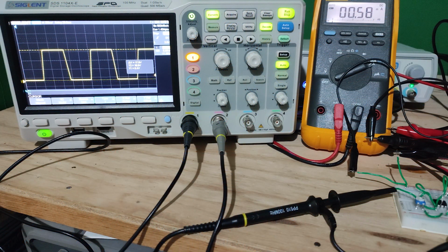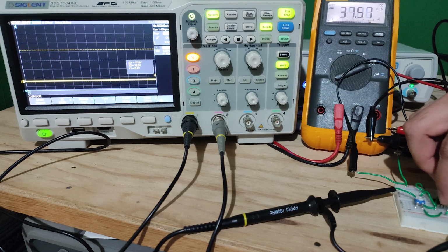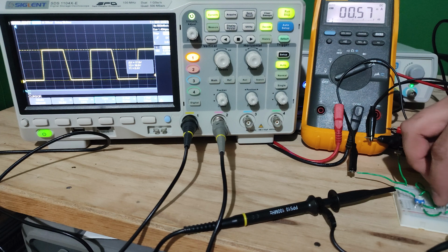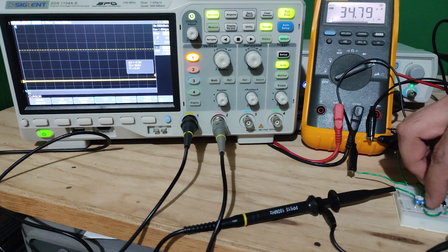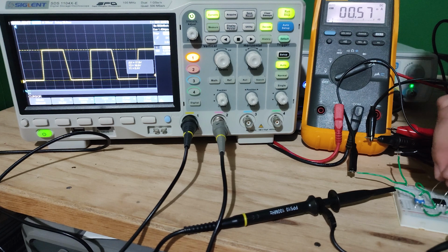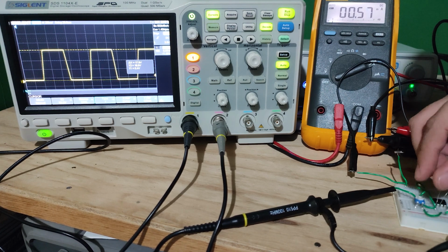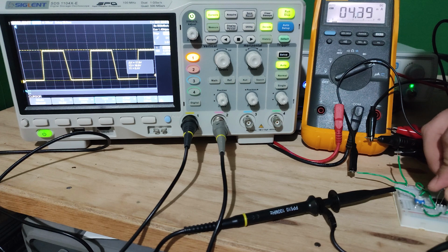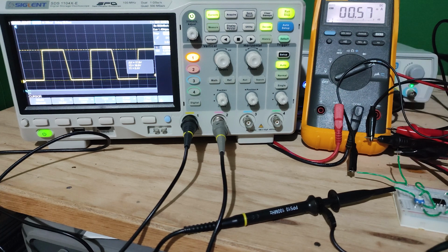So now we are going to test the maximum output current of the op-amp. We have the amplitude on the oscilloscope. We have the current measured on the multimeter, and we can see when we place a load higher than it is specified on the op-amp, which is 30 milliamps, it is going to drop the output voltage because the op-amp has a protection to avoid short circuits. So when a load is higher than it is specified as the maximum output, it is going to protect itself with this measurement or this short circuit protection.